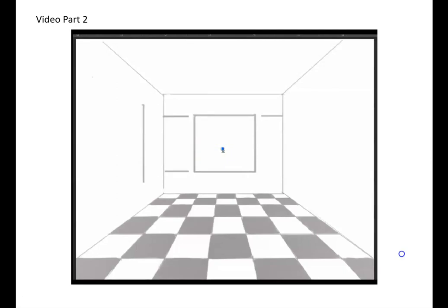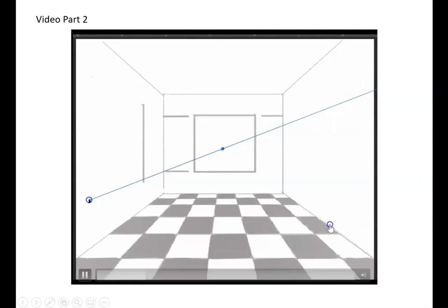And then from the side wall, the line of the height would be going through the vanishing point. And the line of the bottom of the window also would be going through the vanishing point. So you see how my line is going from the vanishing point to this corner where the transfer line meets the corner. And that is what gave me the height of the window.